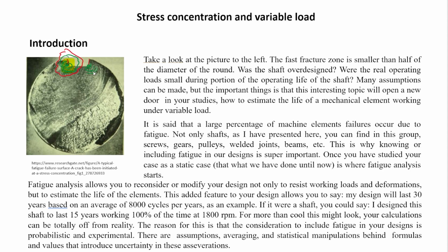Now, in this specific sample, of course, I don't know what the loading cases were. I don't know the operative conditions, such as at which speed the shaft was rotating. I don't know that, but you can also differentiate these two areas. You have the polished area here, that follows this part here, and you have the sudden rupture area, which is this one here.